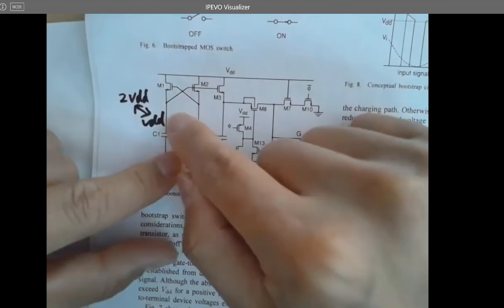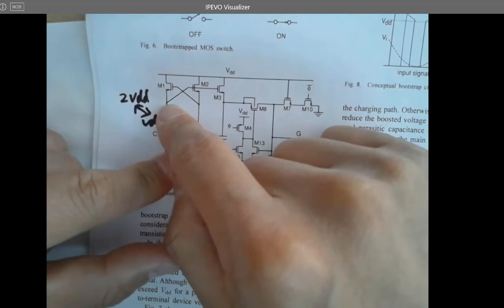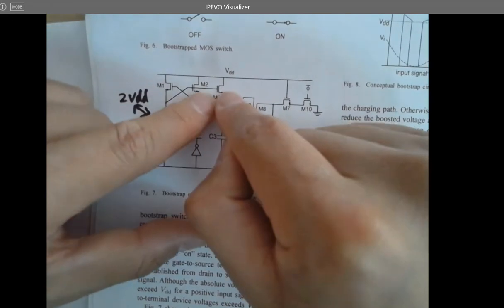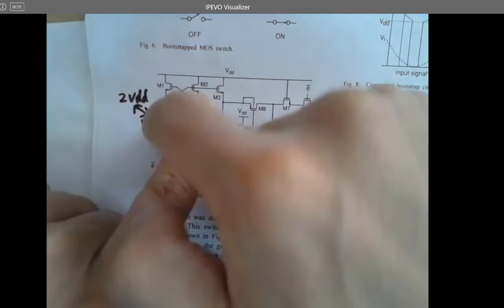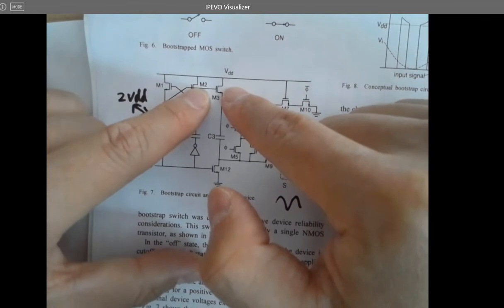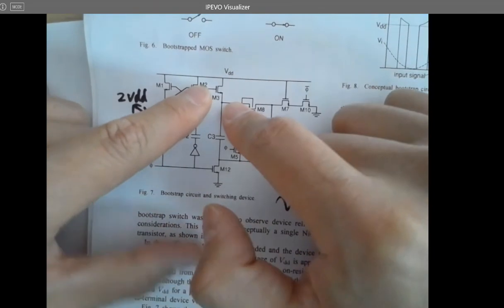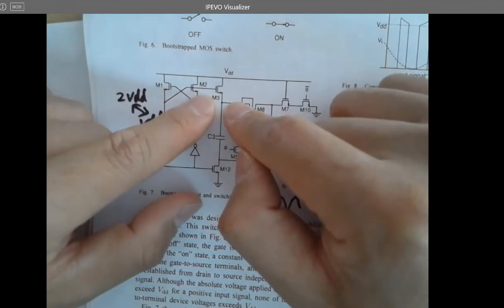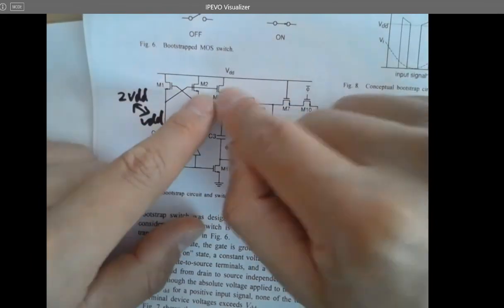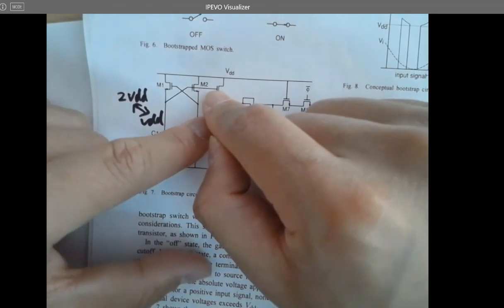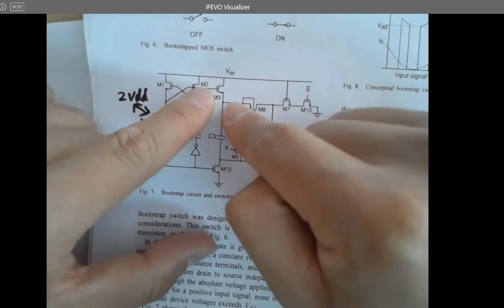So I can have this voltage. Its voltage has been used for the following circuit. So this higher voltage, which is higher than VDD, is being used to turn on this transistor, because we want to use that one to turn on this transistor in order to pass the entire VDD to this point. That making sense? We just covered that at the very beginning of the class. Remember, if we want to pass the entire VDD to the other side of the NMOS, we want to raise the voltage of the gate. And now we have the higher voltage, and now we can pass the entire VDD to here.